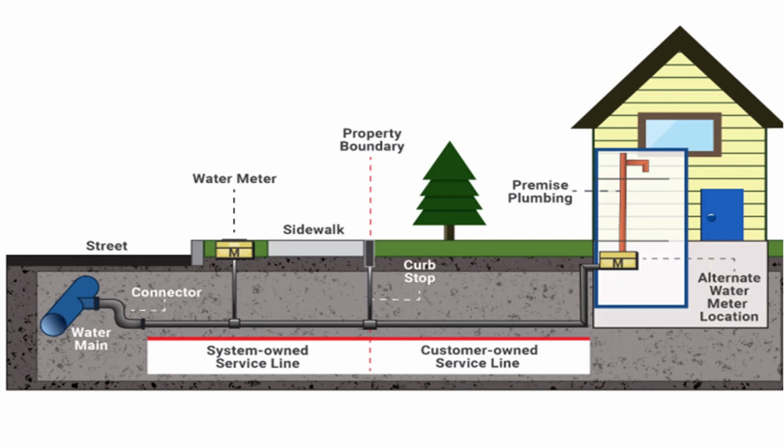A service line is a pipe that connects a property or building to a public water system. As you can see from the image, the community water systems have the system-owned portion and customer-owned portion. Often, ownership of the service line changes at the road curb stop, property line, or shutoff valve or meter box. The pipe's materials on both the publicly and privately owned side must be inventoried.